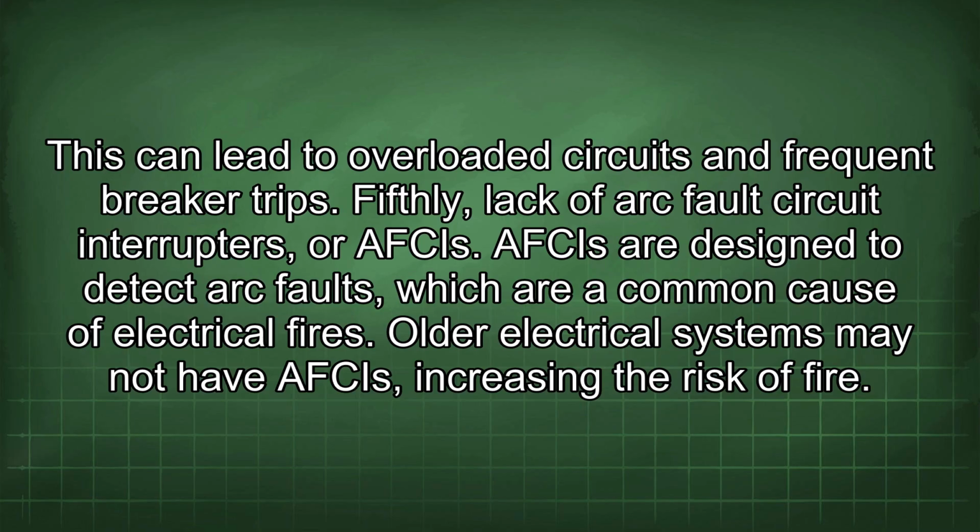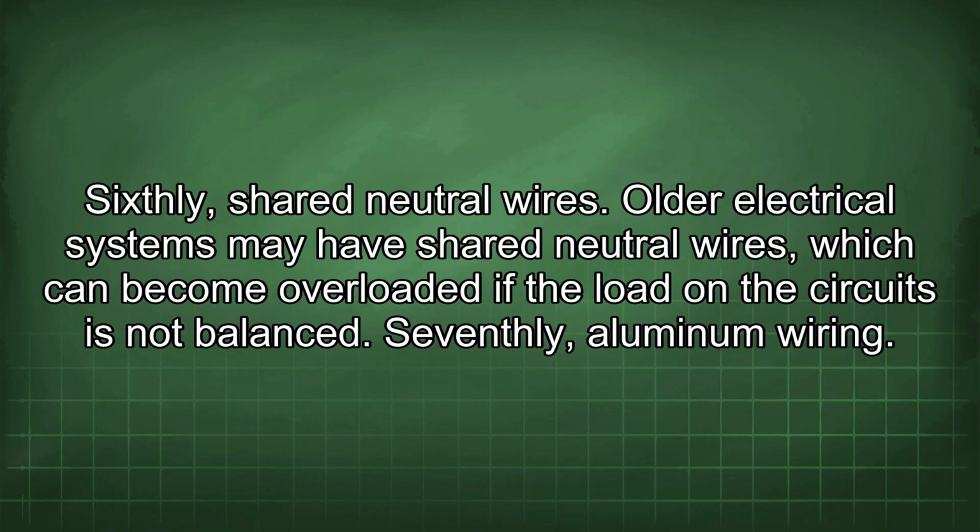Fifthly, lack of arc fault circuit interrupters, or AFCIs. AFCIs are designed to detect arc faults, which are a common cause of electrical fires. Older electrical systems may not have AFCIs, increasing the risk of fire. Sixthly, shared neutral wires. Older electrical systems may have shared neutral wires, which can become overloaded if the load on the circuits is not balanced.